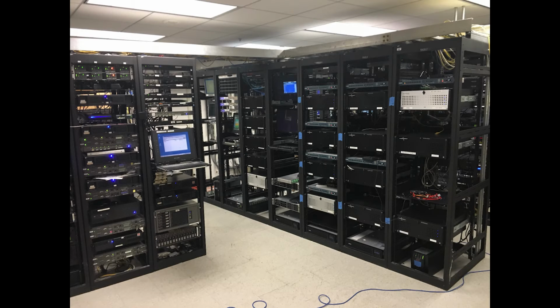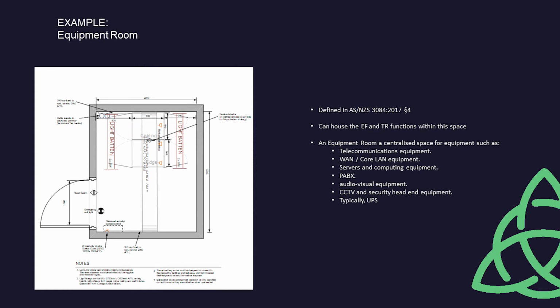The air filtering to the room should provide protection from contaminants. This will significantly reduce the buildup of contaminants in the equipment. It is also recommended that climate control is maintained via thermostatically activated air conditioning that operates 24 hours per day, 7 days per week. The equipment room should also have a positive pressure differential with respect to surrounding areas. This will also reduce contaminants entering the space.